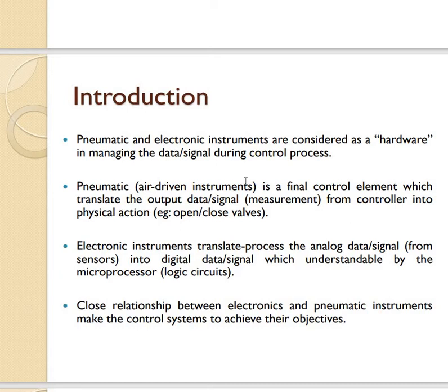So this pneumatic instrument will translate the signal from the controller into physical action. For example, to open the valve or to close the valve, or to increase the valve up to how many percent, depending on the signal given by the controller.